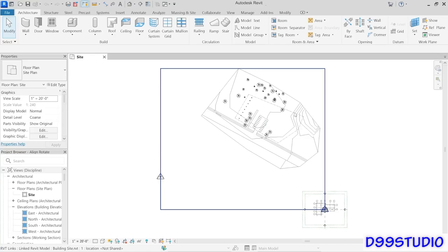Now, the reason why that's better is because by doing that, you're just simply moving the link. You're not actually changing anything in the site model. So you don't have to worry that you're changing the coordinate systems or the reference points or the survey or anything like that. You're just simply moving that link, and it will refresh in place. Okay, so it's going to work perfectly fine.